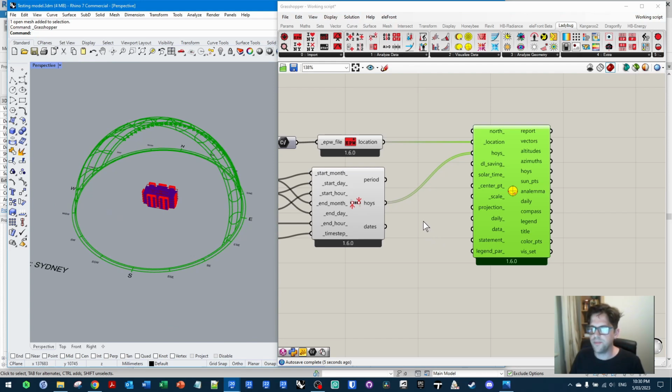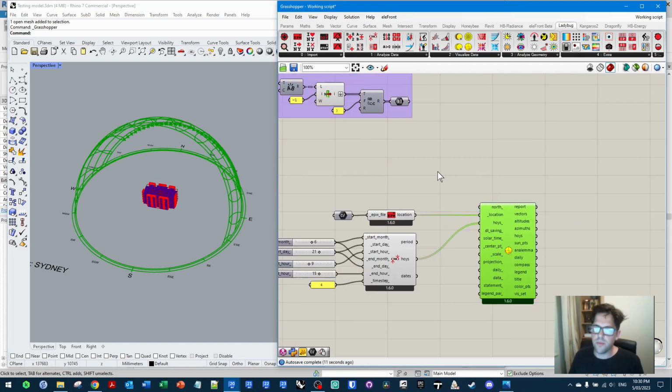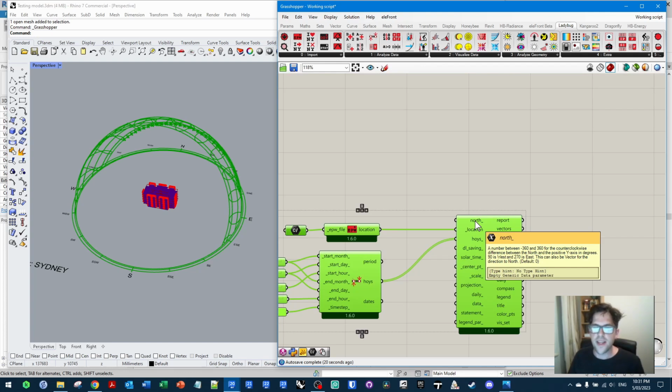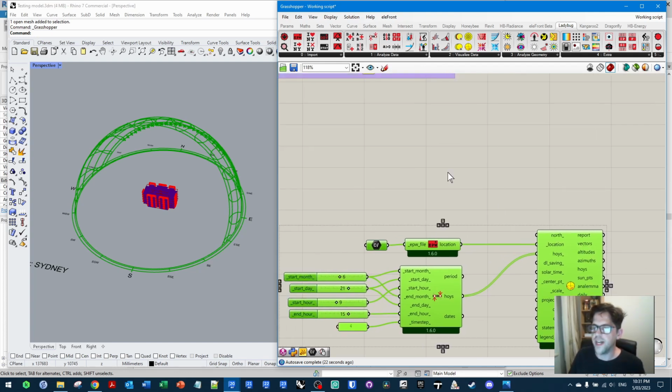There is a slight problem at this point. You may recall that our building was on a rotation, true north was at an angle. Now when we export FBXs, they typically will be facing project north. We could rotate the model manually, but we can also compensate for north as an input in this particular node to rotate our Sunpath rather than rotating our model.